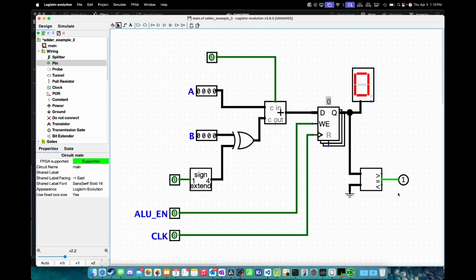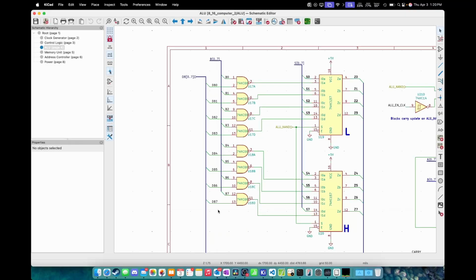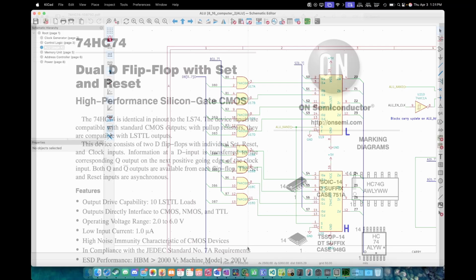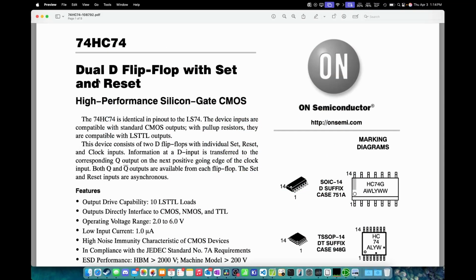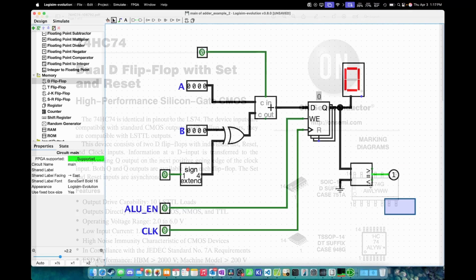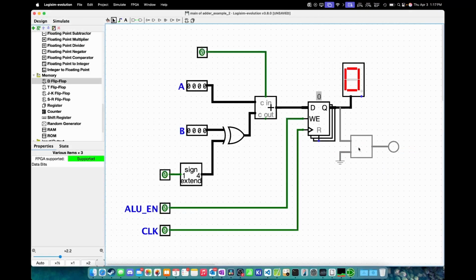Finally, we need to have something in place to store the carry flag. This is necessary because for some operations, we'll need to retain the carry flag while using the ALU logical functions. To do this, we're going to use a simple D-type flip-flop that connects to the carry flag output of the ALU. Now we're almost finished with the ALU.